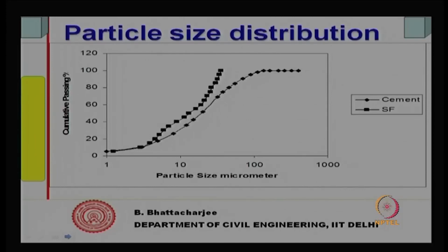Particle size distribution of cement is important. In other words, fineness of the cement is important. Finer the cement, it will react fast, but at the same time it will require more water for wetting or standard consistency. So, particle size distribution of cement is very important. Finer cement can gain strength early. Now, how do you measure particle size and its distribution of cement?